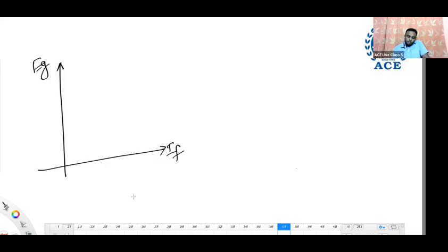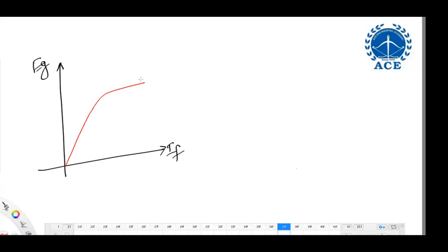But in that case, he did draw it from the y-axis only, sir. He started it a bit up, rather than here. Actually, it is not required. It can start from zero only, because field current zero, flux zero. You can design that material with no property of residual flux, not required. At that time it starts from zero. When field current increases, flux increases, EMF increases. But self-excited generators must start from here.